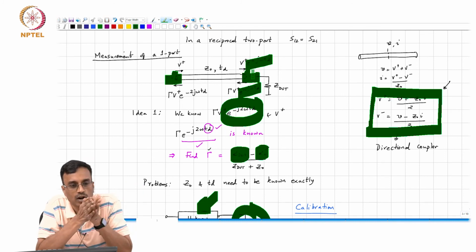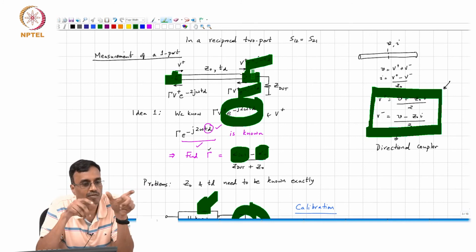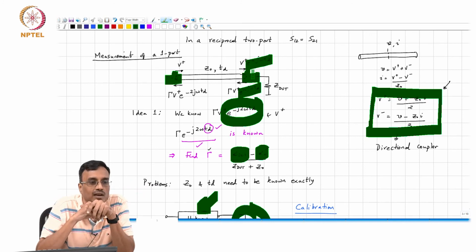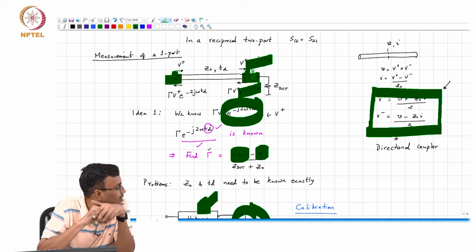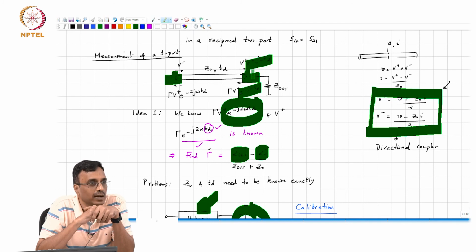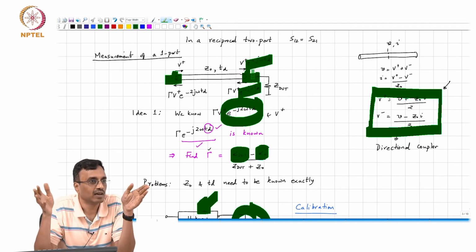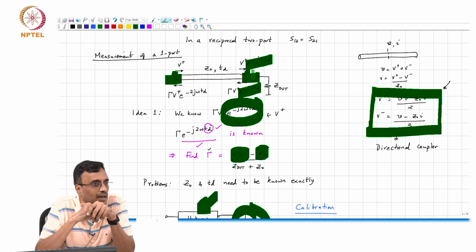If you want that to be a small fraction of 2 pi, which corresponds to the phase of one wavelength, then the length of the cable better be very small in relation to the wavelength. Now, if you are working not at 1 gigahertz but at 60 gigahertz, what qualified as a small distance at 1 gigahertz effectively looks electrically 60 times larger.